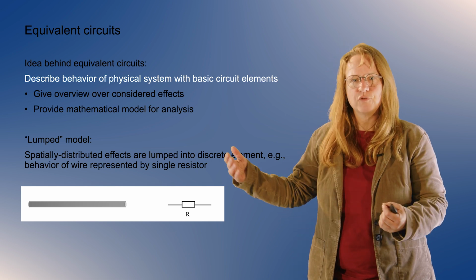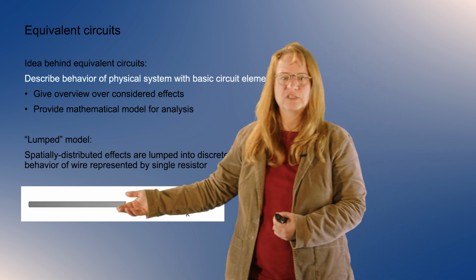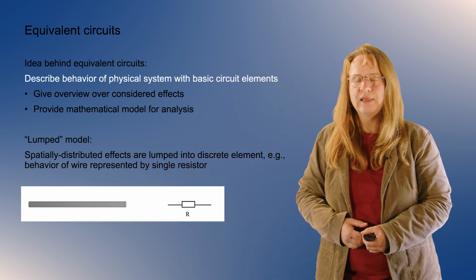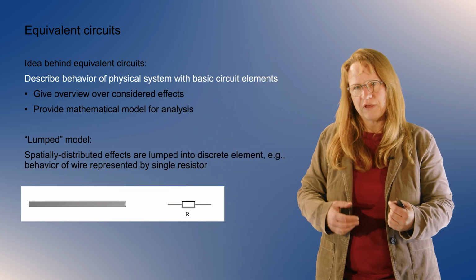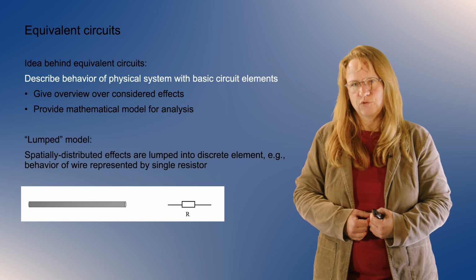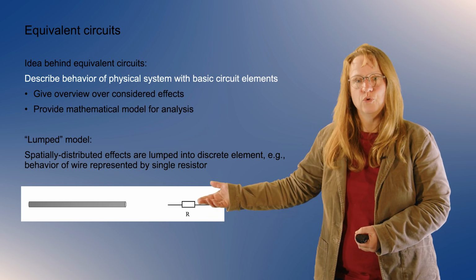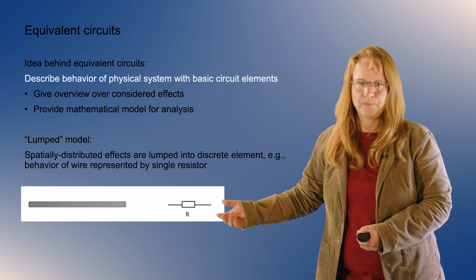If you're going to higher frequencies, at some point you have to consider transmission line effects along conductors, for example. And for that, you have to think of more sophisticated equivalent circuits. For low frequencies, on the other hand, we often can do this simple representation.